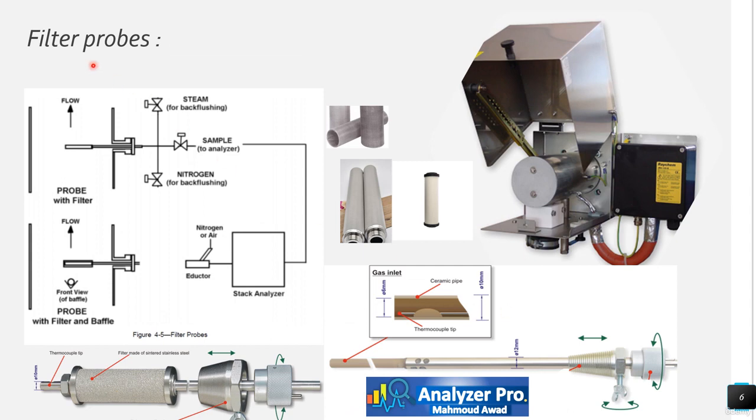Filter probes are generally used in gas streams such as combustion applications when the stream contains significant quantities of particulate material. The filter materials used are primarily sintered or woven stainless steel or various ceramics. These probes must always be located in the process duct in a manner that minimizes their exposure to particulate matter, or else frequent cleaning will be required. Locating the probe inside and just downstream of a bend, or adding baffles just upstream of the probe minimizes the probe exposure.